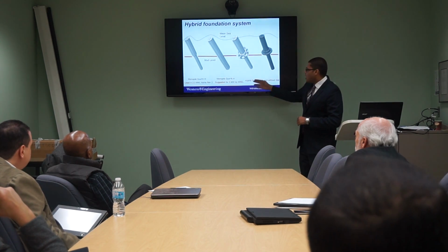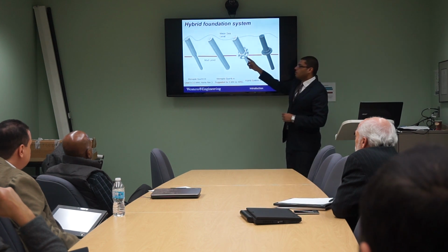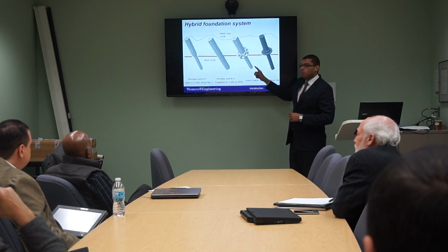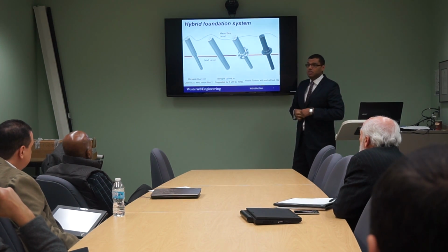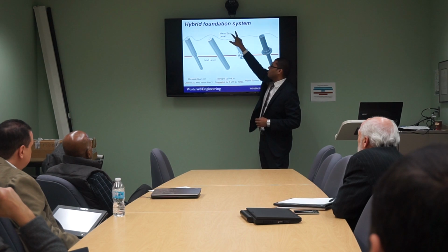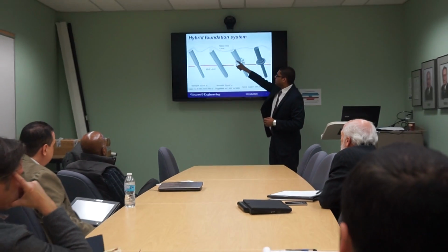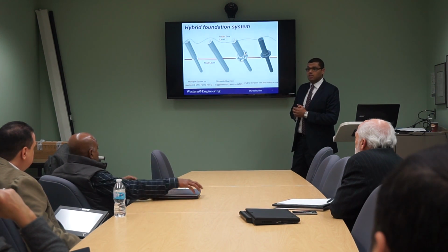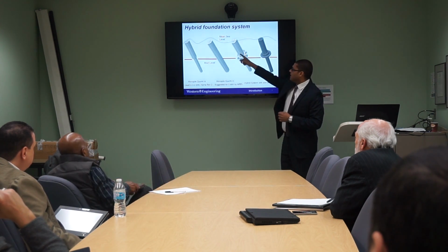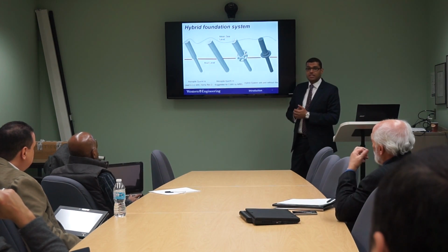And we can see our hybrid foundation system. Our hybrid foundation system will be a combination of a steel monopile with a diameter of 4 meters, which will be connected with an upper part, which will be 6 meters in diameter, to be able to connect with the tower of the wind turbine. We connect both of them by a concrete plate to increase its lateral and rocking stiffness. We can see that the plate will sometimes be with ribs, sometimes without ribs, to see the effect on stiffness.